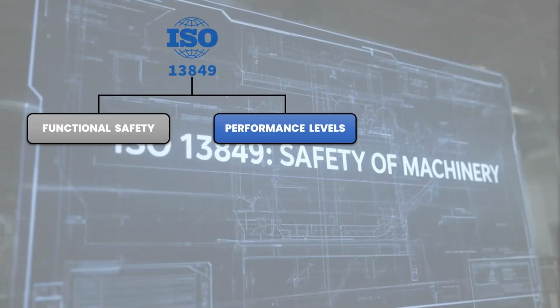ISO 13849 uses performance levels, or PL, to categorize the level of safety on a machine or control system. The standard defines 5 levels from A to E. PLA represents the lowest safety level, while PLE is the highest and most rigorous safety level. The standard evaluates the achieved PL of a safety function using 4 core parameters.